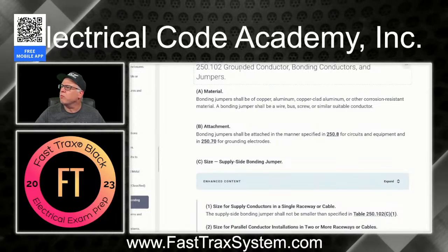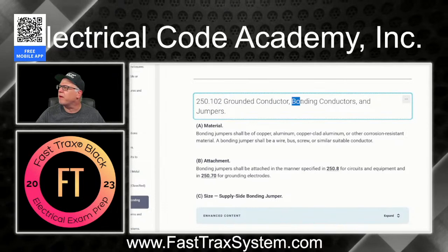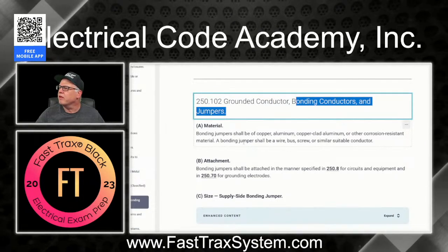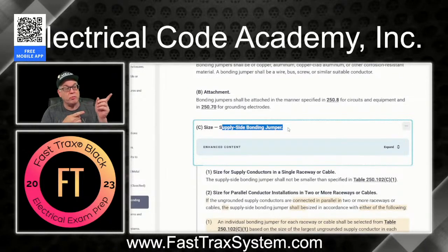So here's 250.102. As you can see right here, it's for the grounded conductor, it's for bonding conductors and jumpers. So that's bonding conductors and bonding jumpers. So here we go. Sizing, supply side bonding jumper. That's what our question was about.